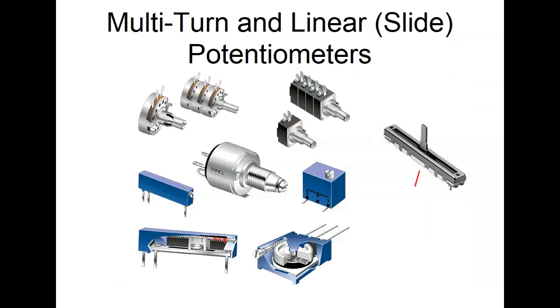So if you look at this one right here, this conductor does not come in. I'm going to turn this little knob right there. That is turning a worm gear, and this guy's turning the actual measurement, the actual pot there. So we're not sacrificing that space to get this center lead through.